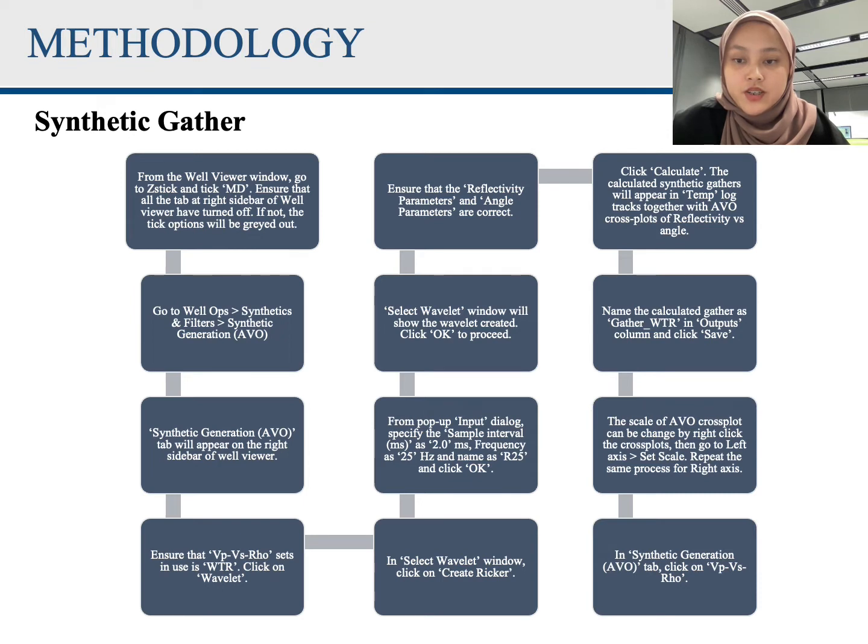Then we ensure that the VP-VS row set in use is WTR, and then we click on the wavelet. In the select wavelet window, we click on create Ricker, and from the pop-up input dialog, specify the sample interval as 2.0 ms, frequency as 25 Hz, and name as R25, and then we click OK. The select wavelet window will show the wavelet created, and then we click OK to proceed.